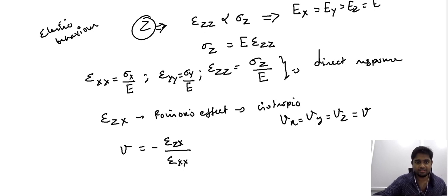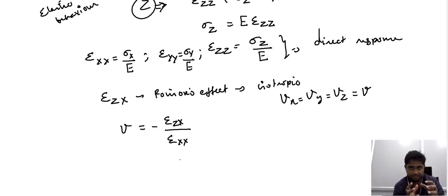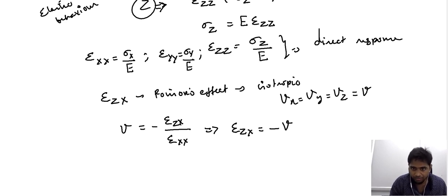So what we end up having is we have considered the Poisson's ratio and the strains along the perpendicular direction, one along the z direction and one along the loading direction. Therefore we have arrived at an expression such as this. Now the response that we are interested in is epsilon zx, and that is nothing but minus the product of nu, the Poisson's ratio, and the direct response along the x direction. Now we have an expression for epsilon xx, which we have derived here.